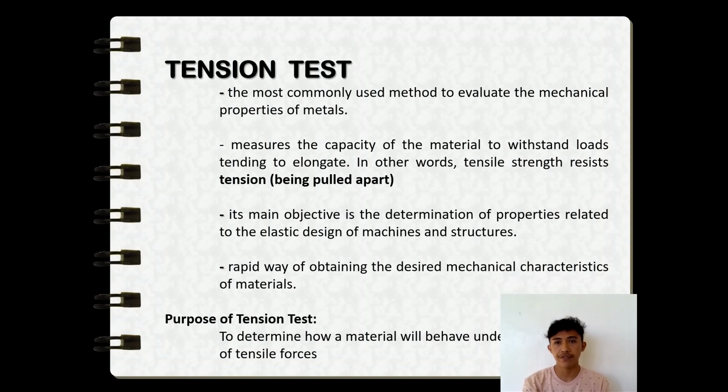Tension testing is a way of determining how something will react when it is pulled apart, when a force is applied to it in tension. It is one of the simplest and most widely used mechanical tests, measuring the force required to elongate a specimen to breaking point. Material properties can be determined that will allow designers and quality managers to predict how materials and products behave in the intended application.